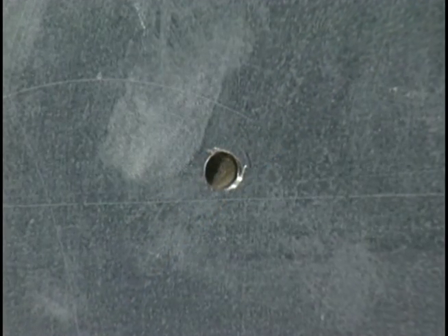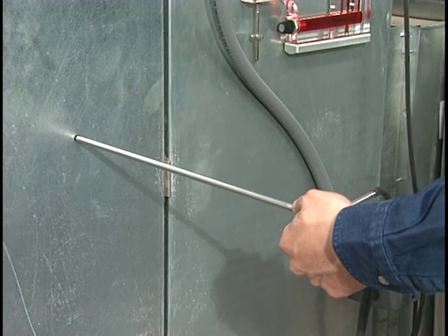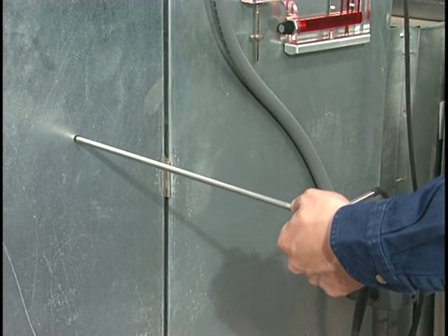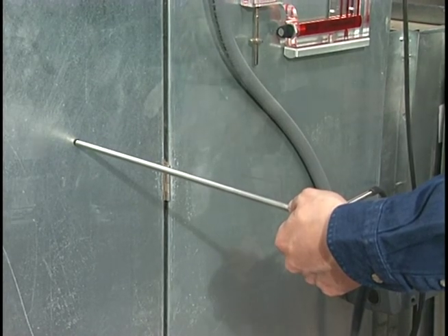To measure static pressure, the technician drills 3/8-inch diameter holes into the unit. These holes are drilled in the unit at accessible points away from filters, coils, or any other component that would interfere with the insertion of the pitot tube.